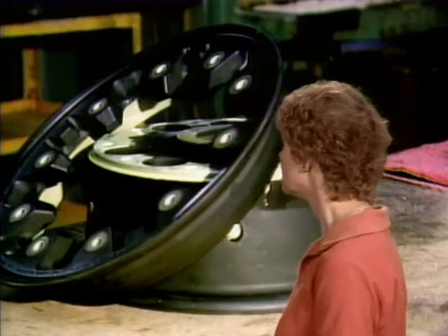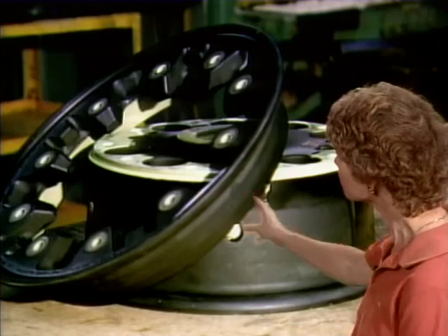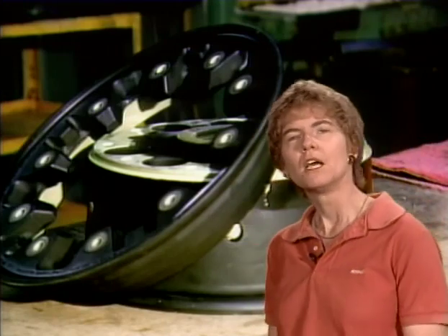Now, let's assume that you've got split rim tires. If you've got split rim wheels, the tire and wheel manufacturers will usually recommend that you deflate the tires before you remove the wheel from the axle. Here's an example of a split rim wheel. This particular one is off of an F-16. But they recommend that you deflate the tires before you even take the wheel off the axle.